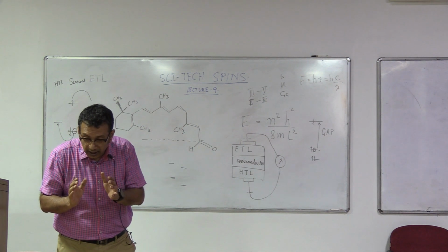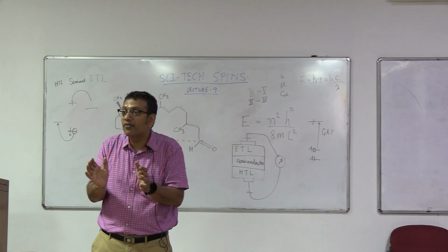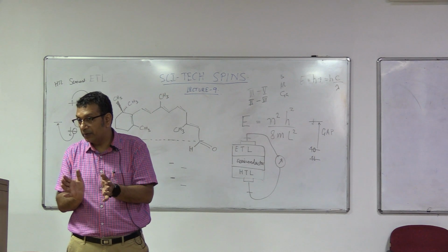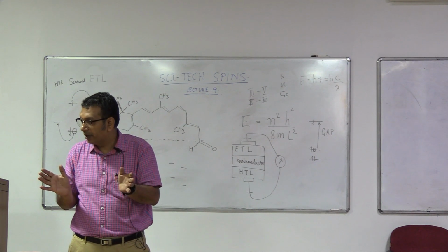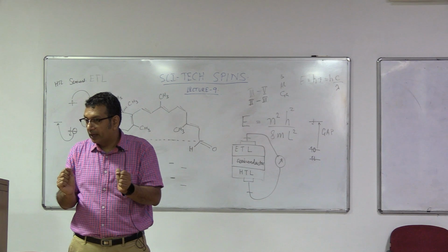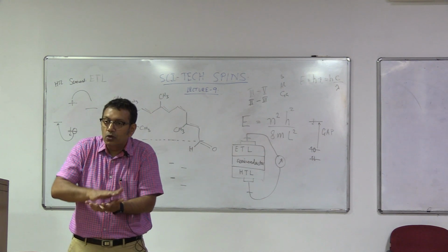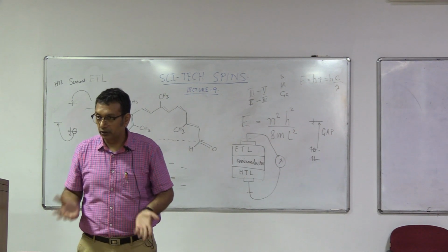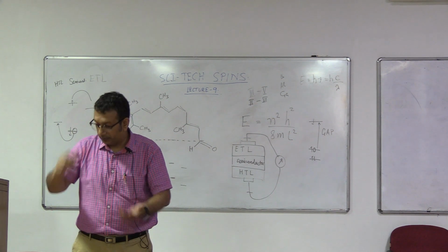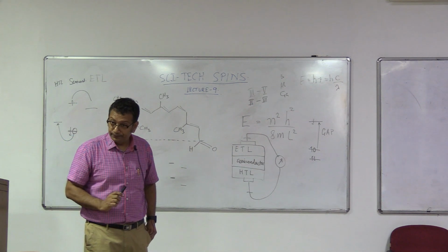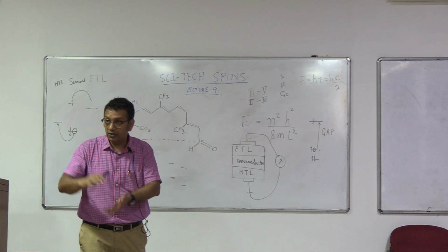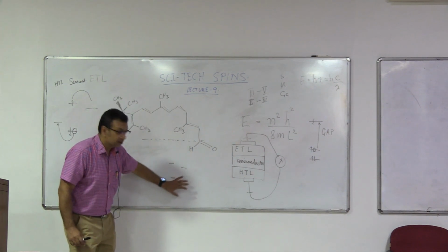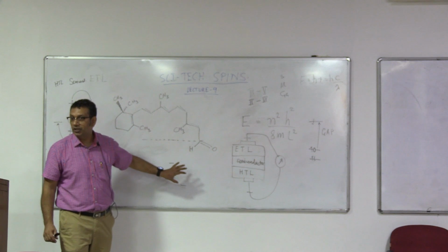But on the other hand, if you can choose two materials which have hardly any strain, and the typical values that the physicists give is about 4 to 5% is the limit, then we can grow one on top of each other, which is known as epitaxial growth. So if you can do that, and you can find the materials which have the correct energy levels, then you can make such kind of a heterostructure.